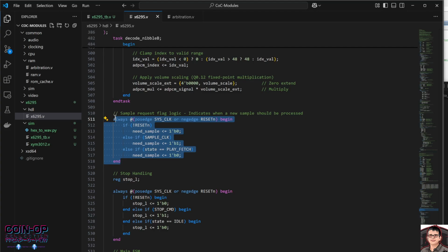So that's it. And then I have this as well. This is what I was talking about. The sample clock is the H blank of the sound world, right? This tells me when I need to output a new sample. I must output a sample when this toggles high. Must. No exceptions. If you don't do that, your audio will be screwed up.